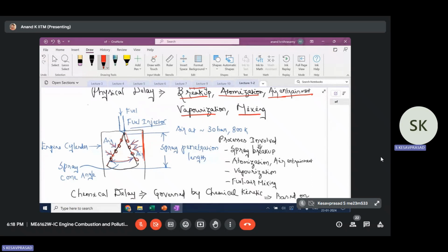Off-road diesel engines generally have a mechanical injection system wherein the injection pressure is typically 300 bar. On-road automotive engines generally use an electronic fuel injection system, wherein the pressure can vary anywhere between 300 and 3000 bar.